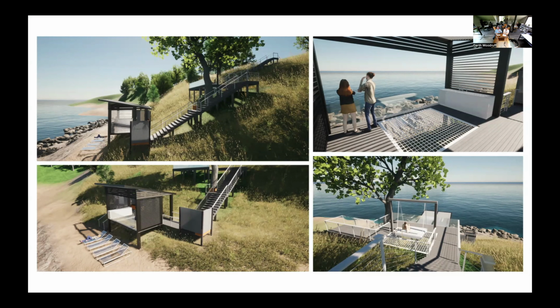So you mocked all of this up in Vectorworks, but you didn't use Photoshop for these. I was going to mention that. The basis of this starts in Vectorworks with that site model I was talking about earlier. But to punch it up and make it look more lifelike, we use a rendering plugin for Vectorworks called Twinmotion. You can work hand in hand inside of Vectorworks and see real-time updates inside of Twinmotion. So you can edit the actual structure in Vectorworks and see those updates happen in the rendering software. They play really nice together.